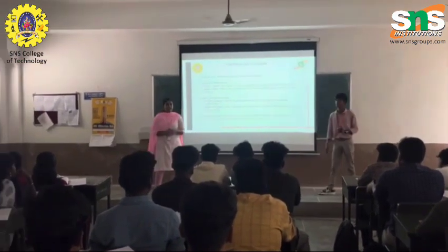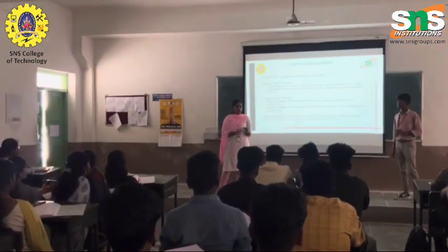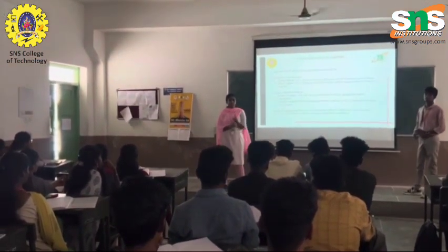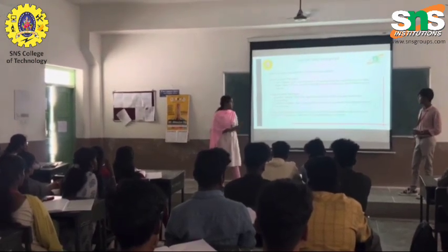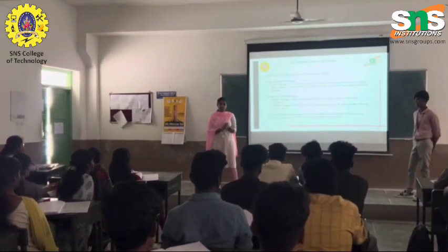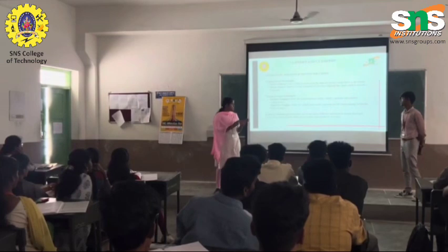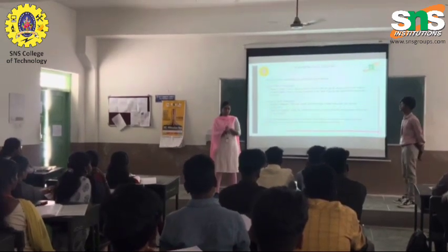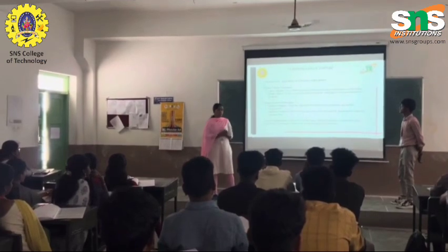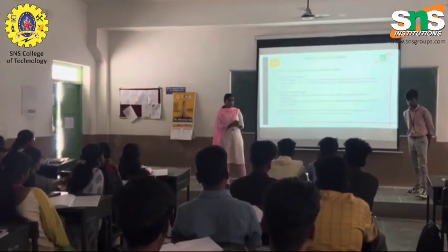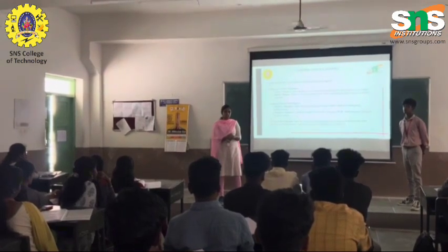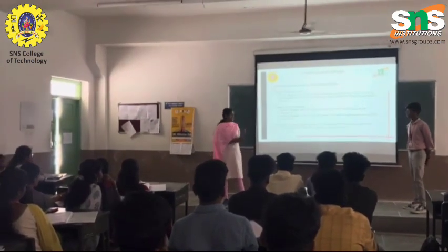The prototype is nothing but turning the circuit into a real world application. First, in clipper circuit prototypes, there are two types. One is the series clipper, in which we use a diode in series with the load to clip the signal that is above the set voltage. And in the shunt clipper, we place the diode in parallel to the load to cut off the signal when it exceeds the threshold voltage. And in clampers, there are also two types.